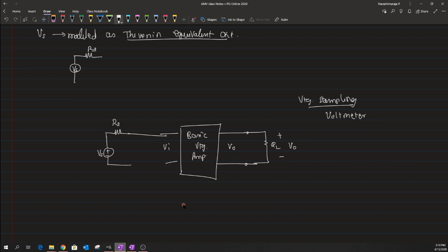So I have to put the two probes in this particular way, and then feed them to this feedback network. This type of structure ensures that we are reading a voltage, and the input that I am feeding here would be the same Vo. This is how I could measure a voltage. So voltage sampling could be thought of as a voltmeter trying to read a voltage across a particular load. Now the mixing has to be connected in series.